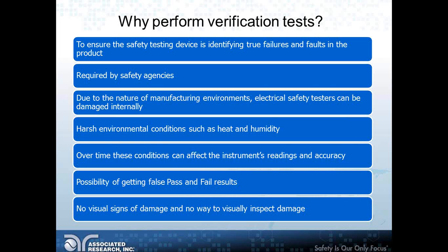No visual signs of damage may occur on your tester, so there's no way of visually inspecting it. The best way is to run daily verification tests on your electrical safety testing device to ensure that it is working properly.